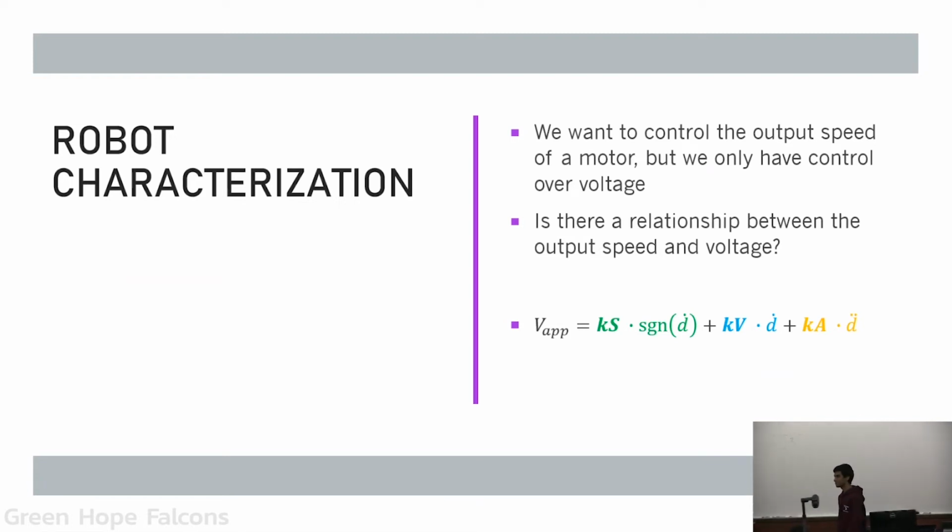Why not? Well, it's really low. You gotta get a little more power to it. I mean, it might move, but like a little bit, probably. So if we said that the relationship is linear, anything over 0 should make it move. But if I give it 0.5 volts now, it's not going to move. Why is that? Friction. Yeah, friction.